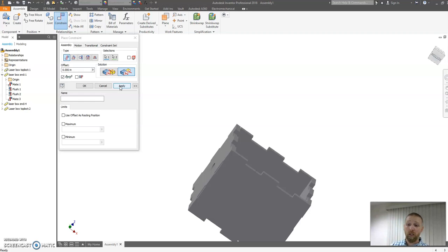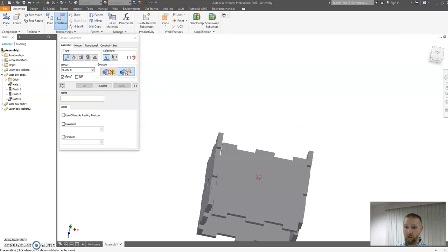If you have questions about how to do things, like you need things offset or off a distance, just ask. Typically, you're going to use this tool. Like if you want it off center, you don't want it right on an edge, you just say how far you want it off. I want it 0.5. You can see right there it moved 0.5 inches off that.